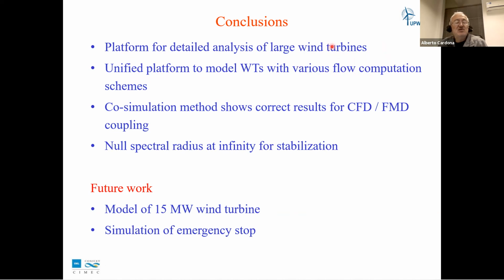The CFD is for detailed modeling. The co-simulation method showed correct results for CFD and flexible multibody dynamics coupling. And it's important to set a null spectral radius, zero spectral radius at infinity, for stabilization of the flexible multibody dynamics.